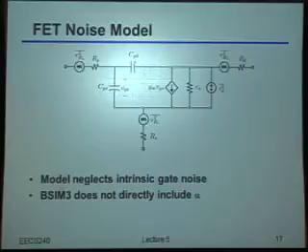Okay? Now, of course, the somewhat bad news is that many of the effects that we've mentioned may or may not be directly captured by your SPICE model. Okay? So if we draw the sort of small signal noise model that you would typically see, as I mentioned before, you typically won't have the gate leakage or the gate noise intrinsically built into the model, just because it didn't really used to exist, and so it's not part of the standard model decks that people come up with. So again, watch out for that.